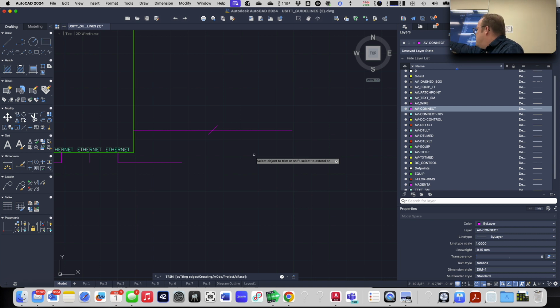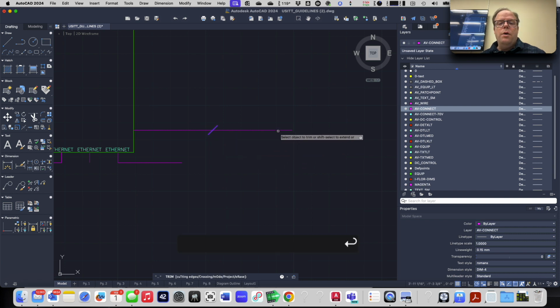And you see how there's a capital T in cutting? Yes. That's not just a mistake. The capital T is meant to tell you that if you type T, enter, then you will be in cutting mode. Okay? So I do T, enter, and I will select that diagonal line. Enter. And now, if I click on the line, I will know for sure that it cut to that spot. And then enter. There, I've trimmed.